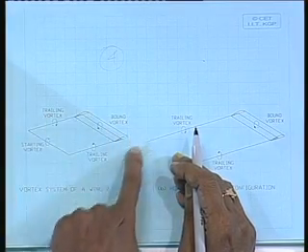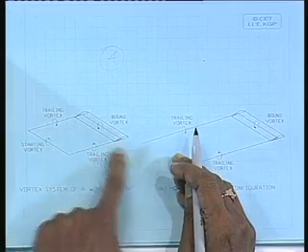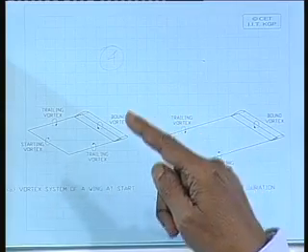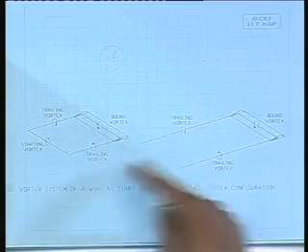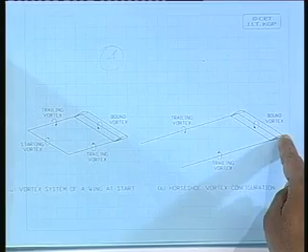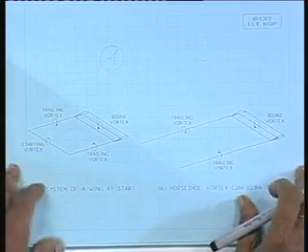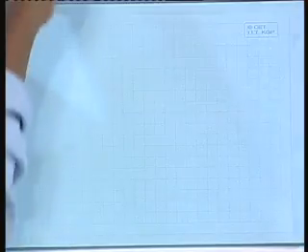The force on the propeller blade will come only due to the bound vortex here, which is around the propeller blade. Shown here is a constant strength circulation. Okay? Right. Now, this can be extended to the propeller.